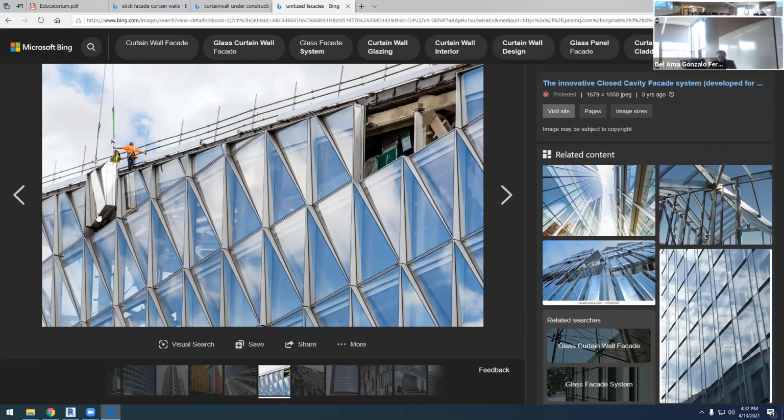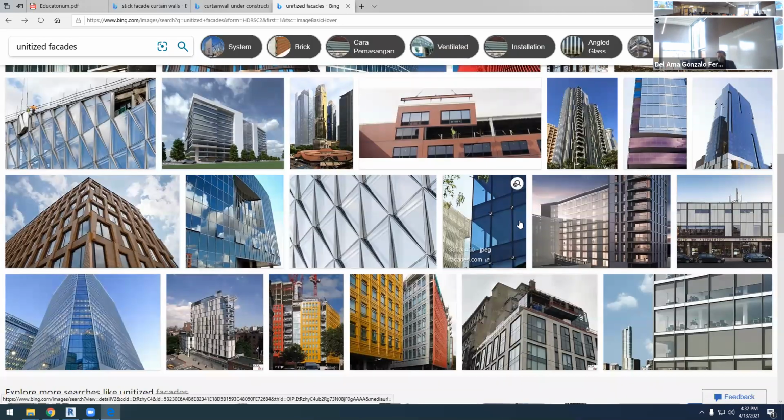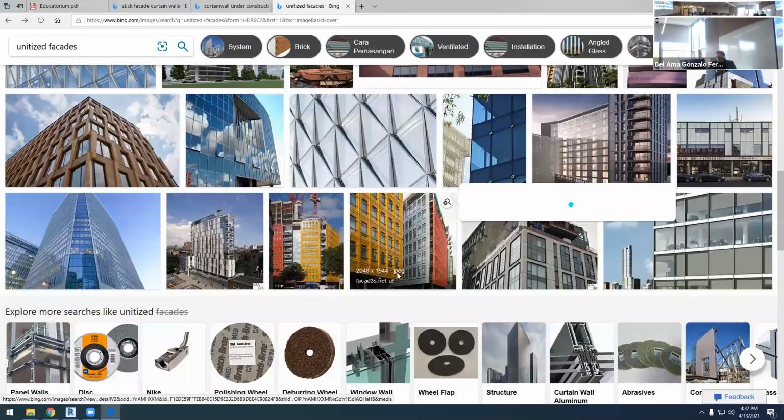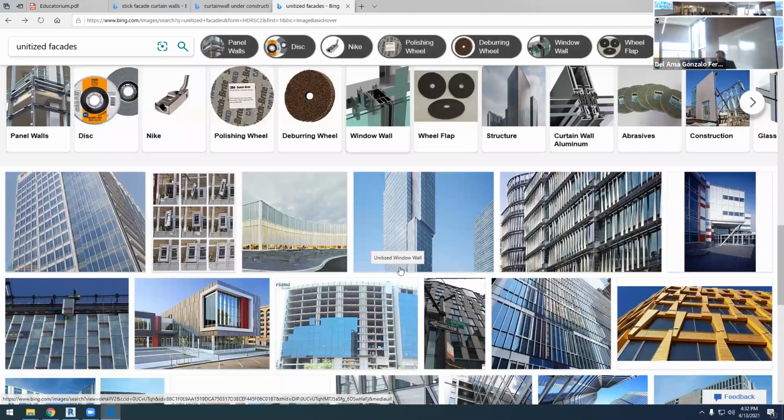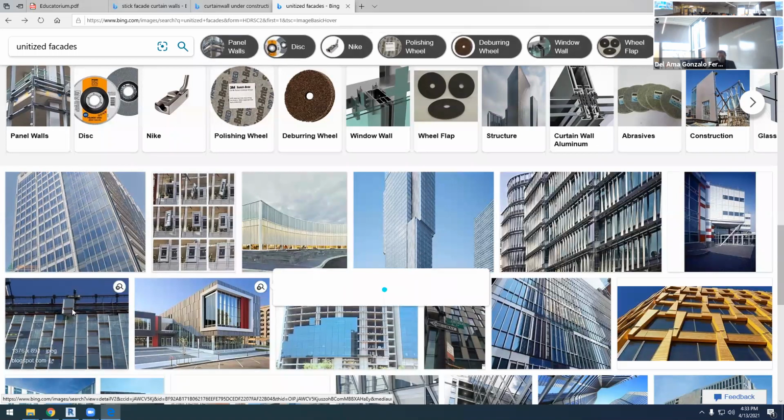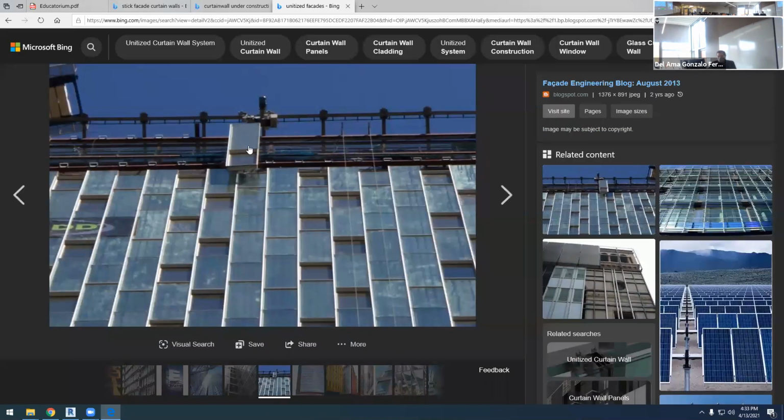Okay, this element itself comes from the workshop with the right measurement, and all the elements, the aluminum frame, the glass, everything is on it, and then you only have to place it. So this is more reliable because the more things we can do in a workshop, the fewer mistakes we will have on site. On site, the working conditions are tough. It can be raining. So if you prepare everything in the workshop and then you just bring this element into the site, then you place it and that's it.